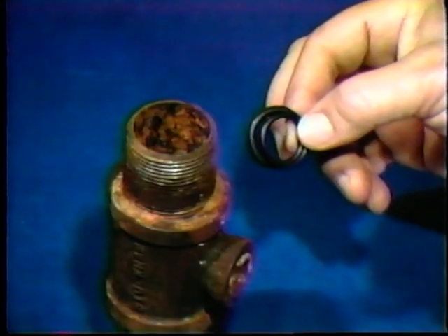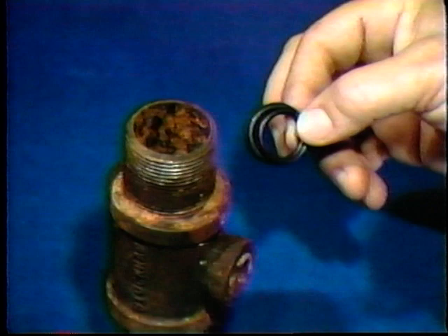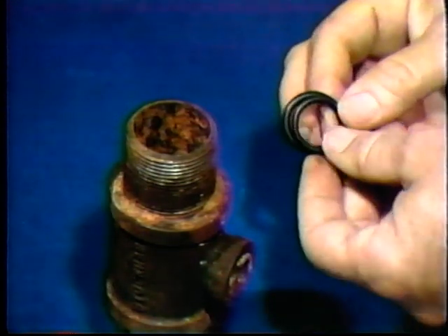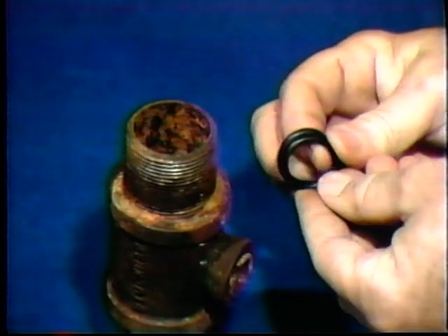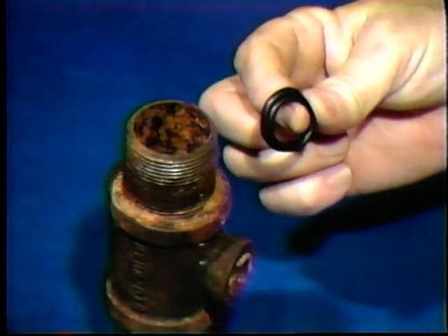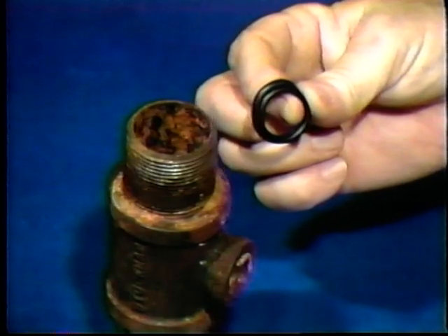The problems you see here, a rusty pipe, and this seal that has deteriorated and swelled up, were both caused by the same type of contamination, entrained liquid. Entrained liquids are liquids that enter the system along with the air. Probably the best example is water. It's present as moisture vapor and can get drawn in through the air intake. It can cause the rust and seal damage we have just seen.